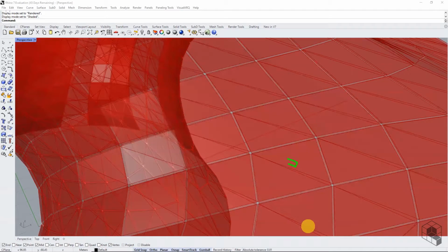For this exercise, we will provide rectangular slots of size 0.8 by 1.5 mm. One slot will be provided for each triangular face at the diagonal intersection, such that a cable tie can loop through and lock in place.